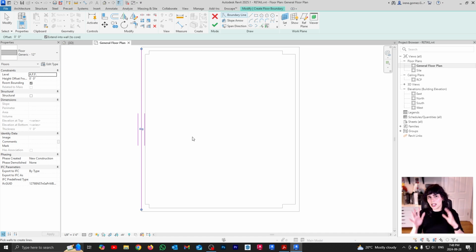But basically the idea in the context of Revit is that usually if you have a multi-story building, you're going to want the boundary of your floor to connect to the core of your wall, but then whatever exterior finish your exterior wall has should wrap in front of that floor. Now, if your building is, let's say, a concrete structure with a curtain wall facade in front of it, then in those cases we want that floor to end right against the outer side of our walls. It's basically flush, and then the curtain wall system goes in it.